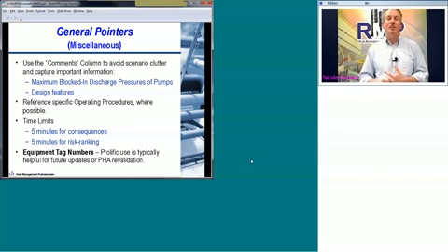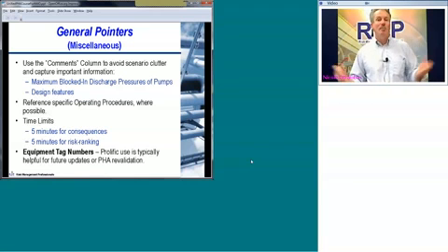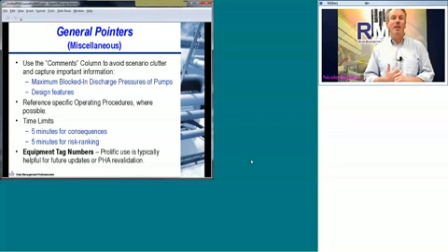Also, risk ranking. If they're going around in circles because it's a contentious issue, it's okay to leave it unranked and put a recommendation for somebody to go back and maybe apply some quantitative techniques, maybe LOPA or some of the other things that are out there to actually resolve the risk ranking.